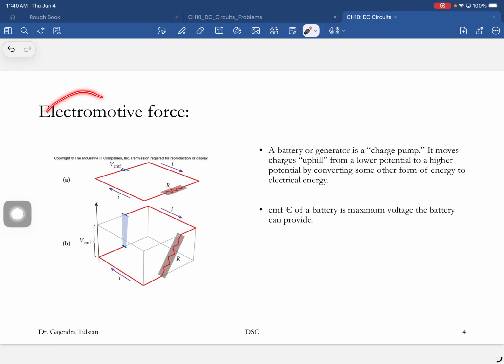All right, so here's a battery. We've seen this circuit before. Here's a battery, and here's a load connected to it. What the battery does is it establishes an electric field in here. The electric field points in the direction of decreasing potential, and here's the potential profile. There's not much of a potential drop along the wires because the resistance is very minimal. If this was a 12-volt battery, that means there's 12 volts here, and this is 0 volts.